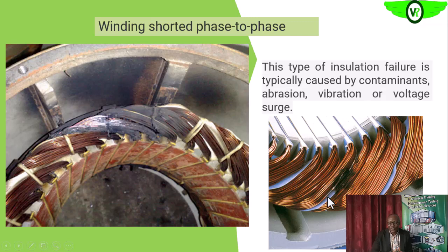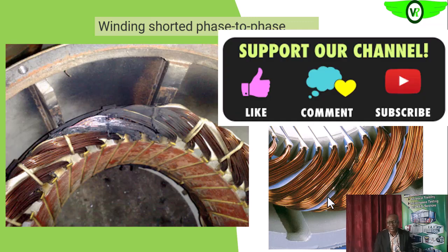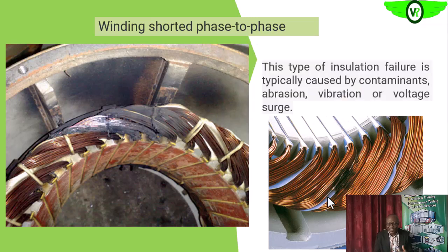So if we have a power quality monitor on our system, what we need to do is look at the input power quality pattern to see if there are surges. If we suspect surge, then we can put a surge protector on the line to the electric motor, so that when there is surge in the future, the line will just open up and protect your electric motor.